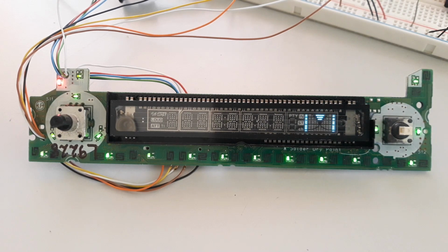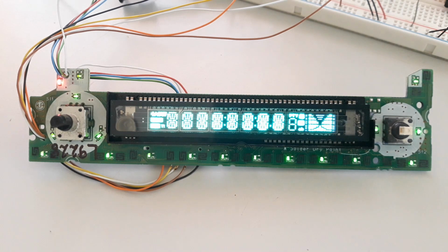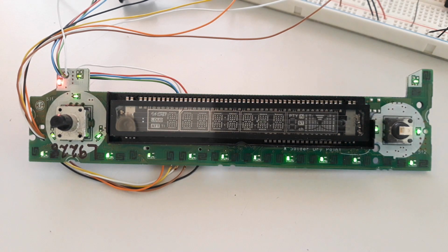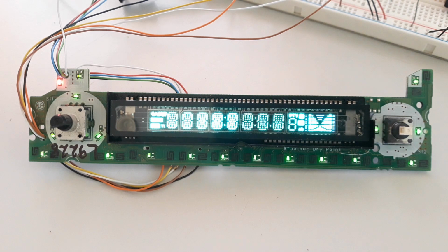It is implemented in the car radio panel with a CD player, as it has a space on the PCB for the CD input. It is a driver with direct control of 82 segments, and each of the three possible grids can be accessed individually. This results in a total of 246 segments.